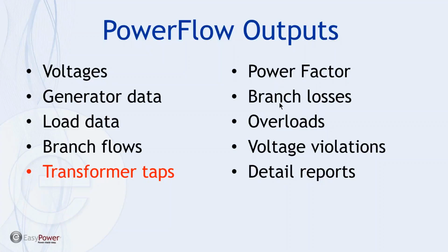And then the ability to trend and compare the losses, either in the current flows through the branches or the voltage drops at any particular bus. If you track those and the delta between the model and the real system, that could give us an indication where we have a trending issue that merits preventive maintenance, or at least locating the source of the difference over time.